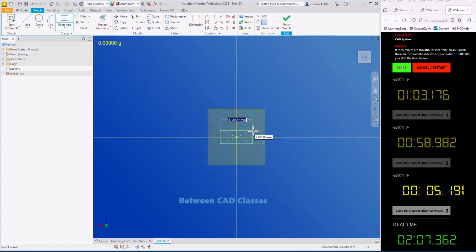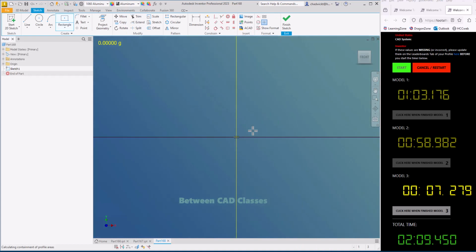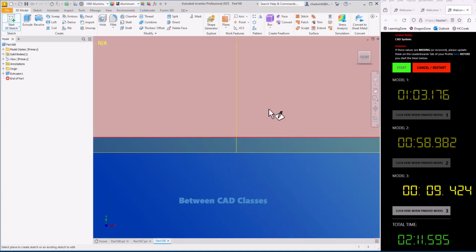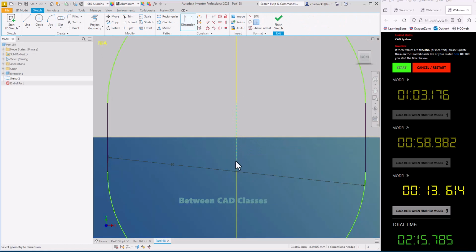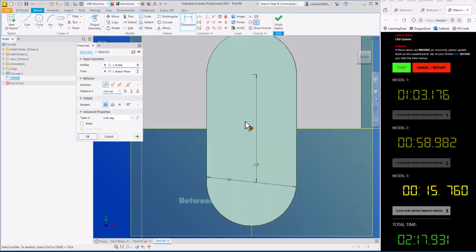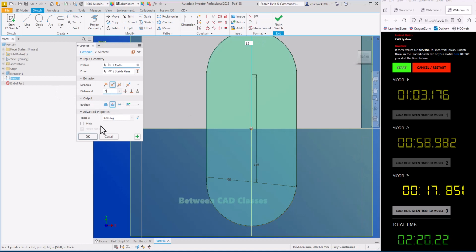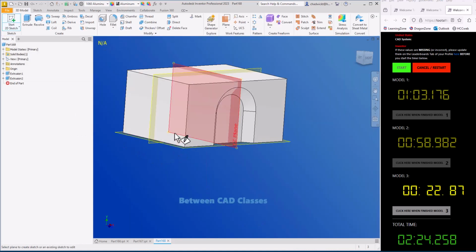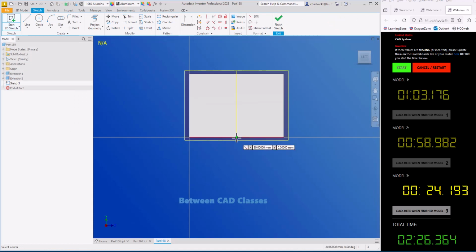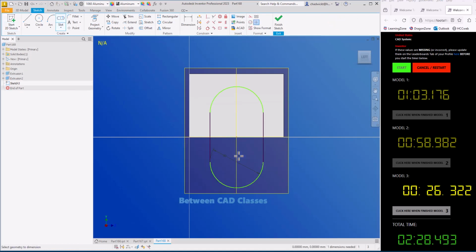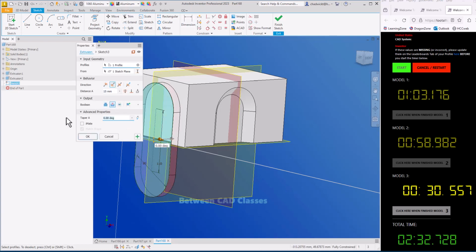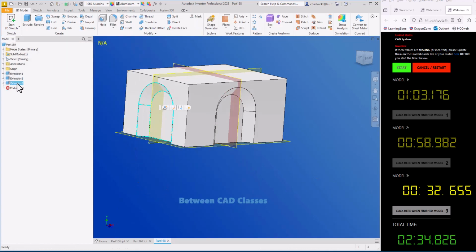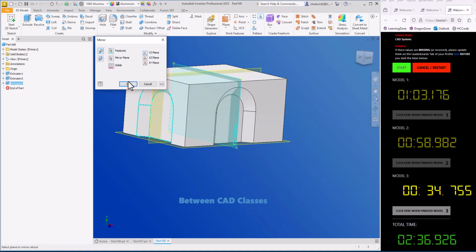Then finally the third part, I start with an extrusion, and then this has a slotted cutout feature with some draft angles on each side. And this is definitely where I spent most of the time on this particular part. I wish I could find some easy way to copy this cut feature to the other side. It was difficult to do so since they have different rectangular shapes, so I just simply had to create the shape again. Then I mirrored these cutouts across the part.